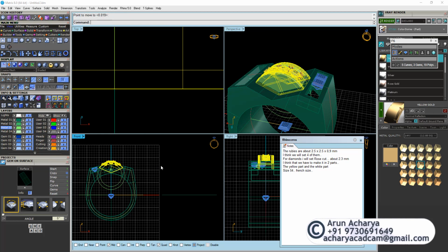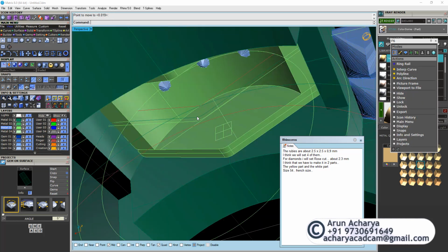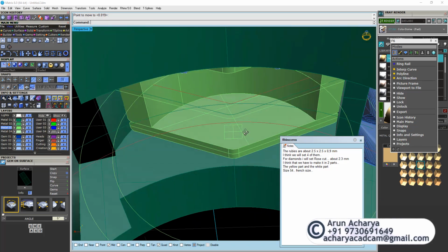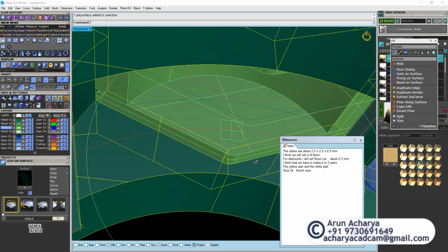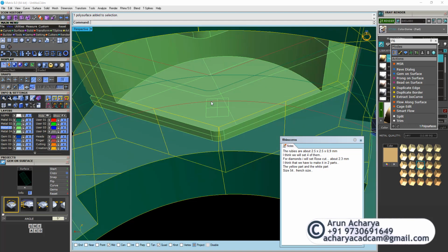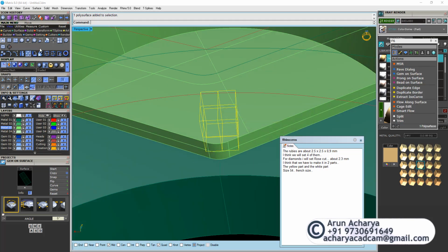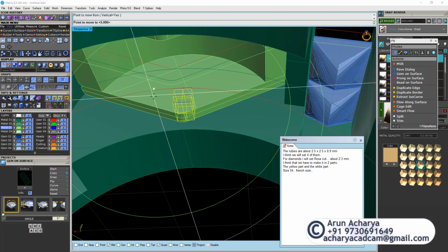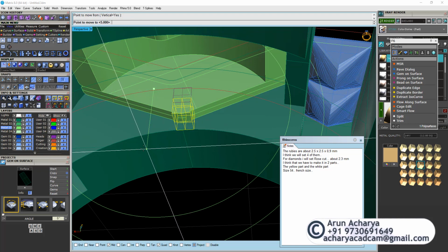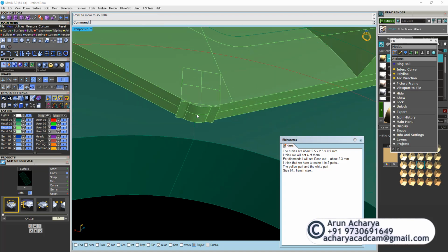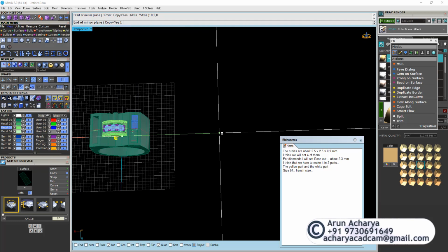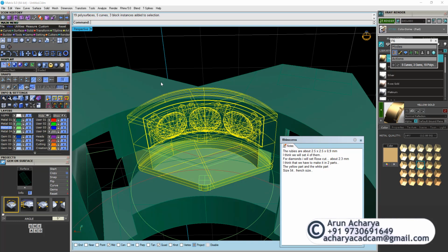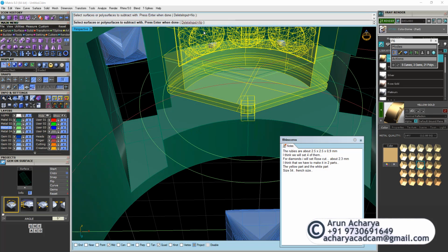5 millimeter, we raised it. Yeah, you see, that's fine. So what I can do now here, I can just extrude this down, or I can bring this down to mark a cutting point for this, which can be this one over here. Okay, so copy this to the other side and just do a Boolean difference, and we click on no. Okay, that's fine.